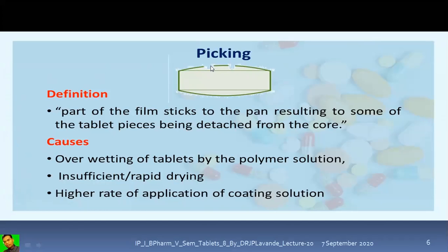In tablet compression, as a tablet defect, there is also picking. It is because the surface adheres to the upper punches, and during ejection, as the punches move in the upward direction, that portion gets removed.